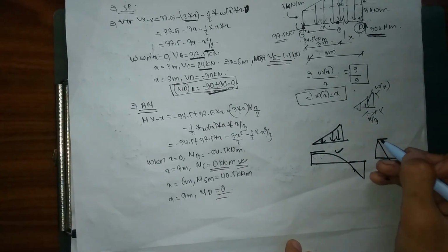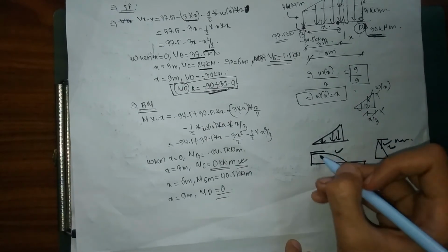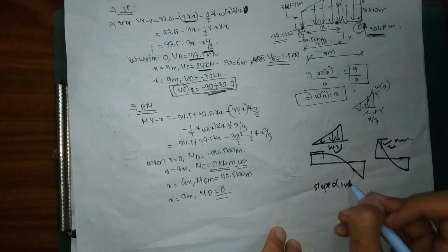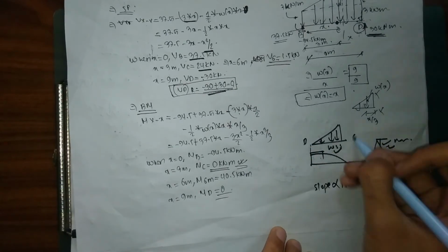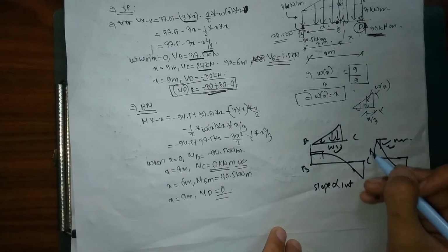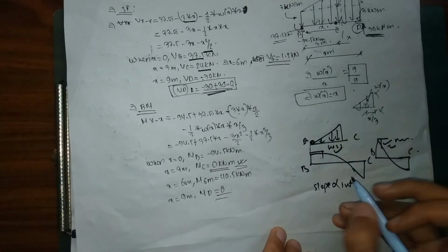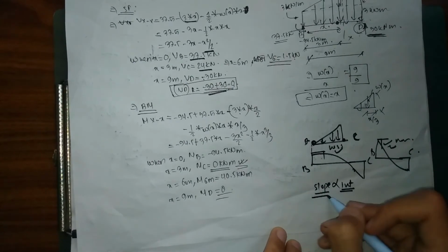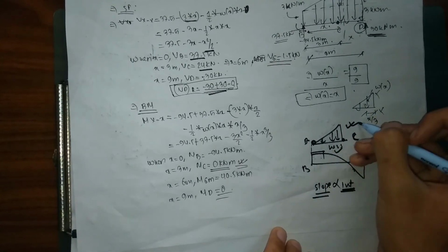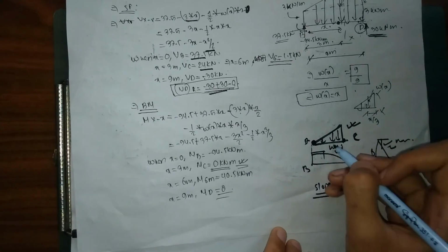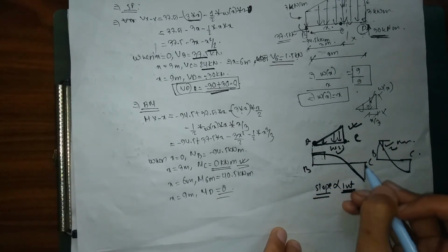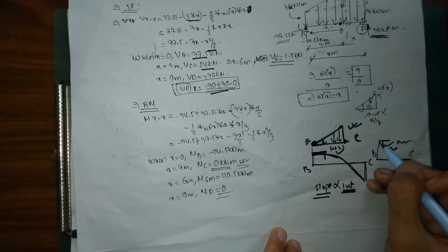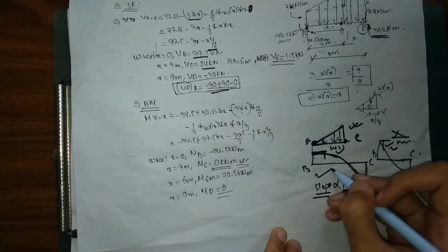As you can see here, the slope of this curve is more, while the slope of this is less, and our slope is directly proportional to our intensity. If we're talking about B and C, this is my B part and this is my C part. At B part my intensity of the load is less, while at my C part intensity of the load is high. Slope is directly proportional to intensity, which means while I'm moving from B to C, I'm going to have this sort of figure, where the slope is less at point B because intensity is less. So we do not draw this figure, but we draw this figure.